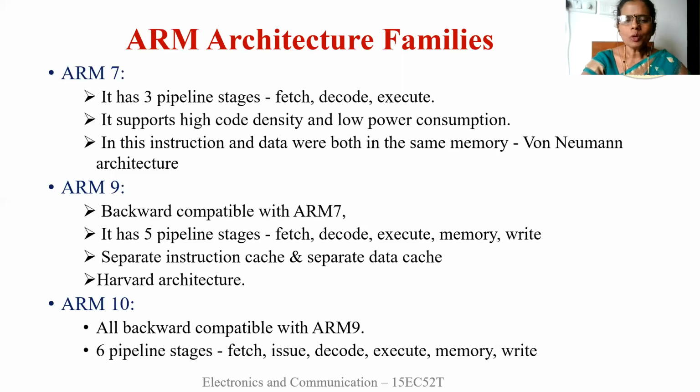And it has got one more stage called the write stage. In this stage, the fetched value is written back to the register present in the instruction. So what is the register present in the instruction? The fetched value is written back to the register. It is called write. So this feature we are not going to study. We are going to study only these three: fetch, decode, and execute, not memory and write back, because we are studying ARM7.